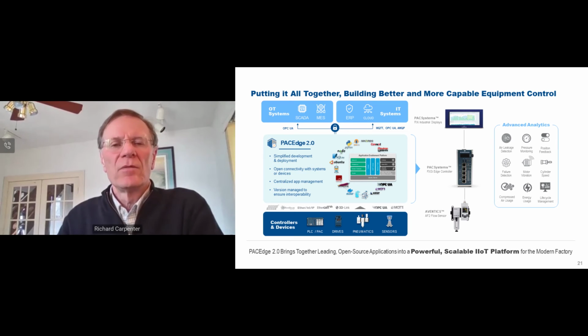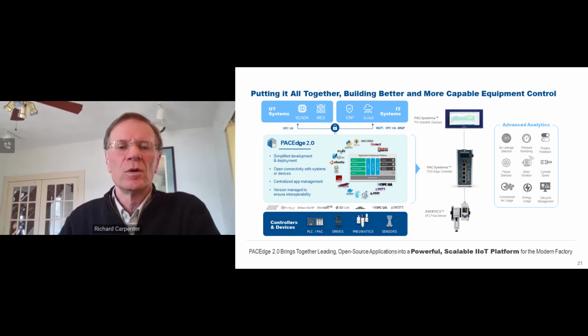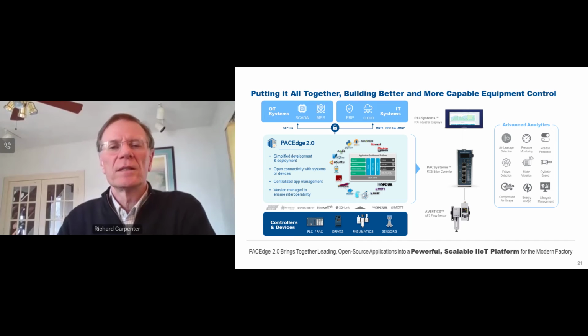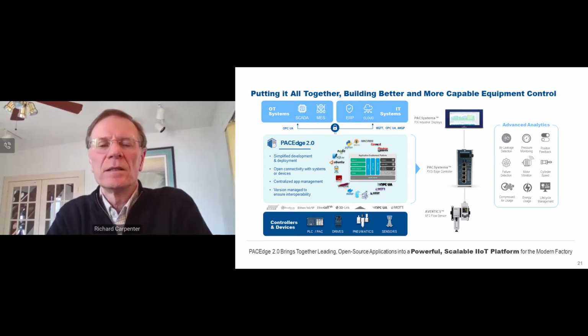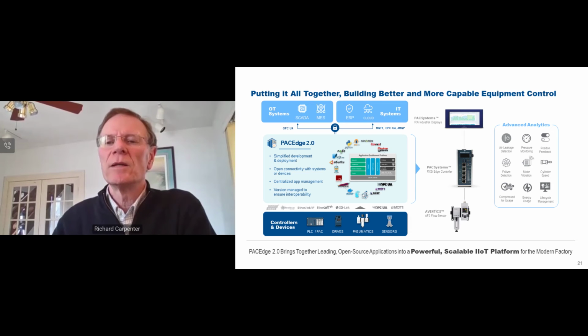So you can see it here in terms of the application. The package application is the IoT-enabled side, and that's what allows us to close the loop, as I discussed earlier, with connecting to not just the control system, but the other devices that are in the network in the bottom dark blue section, and then deliver a set of advanced analytic applications, taking that little data, analyzing it, and providing some insights to the operators. It might be around the air leakage detection that I talked about before. It might be some pressure monitoring. It could be position feedback on the servo or the pneumatics or some other device, because you're trying to understand if maybe you've got more friction than you had before, so you can proactively do service to get the equipment operating at peak performance.